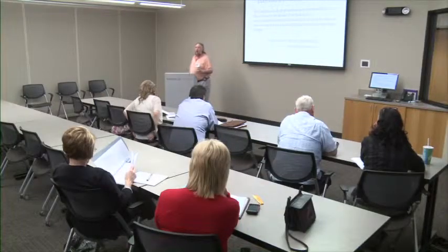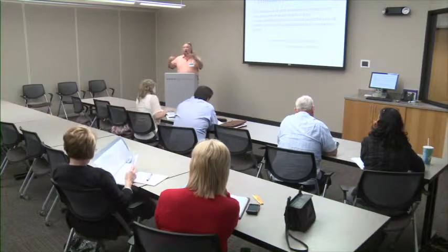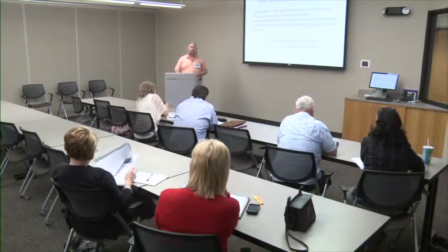If I've got 1,000 yards of dirt to move and I can move 10 yards an hour, I can move 100 yards in a 10-hour day, 80 yards in an 8-hour day. If I move it in a 10-hour day, it takes me 10 days to move the dirt. So now I have a duration for my activity of earthwork. With this activity and duration, I now have a piece to go to my schedule. I know how long something takes for me to do.